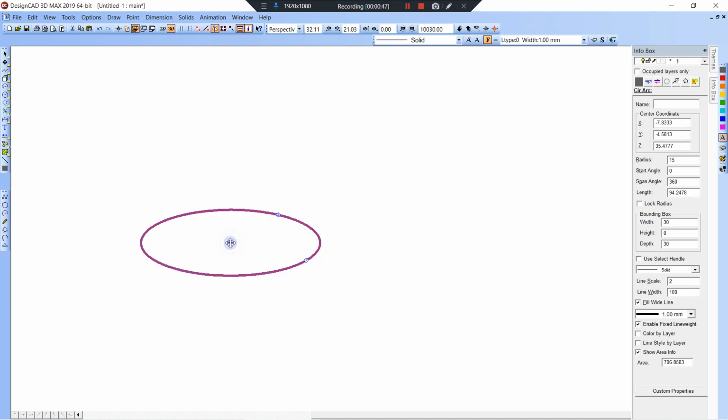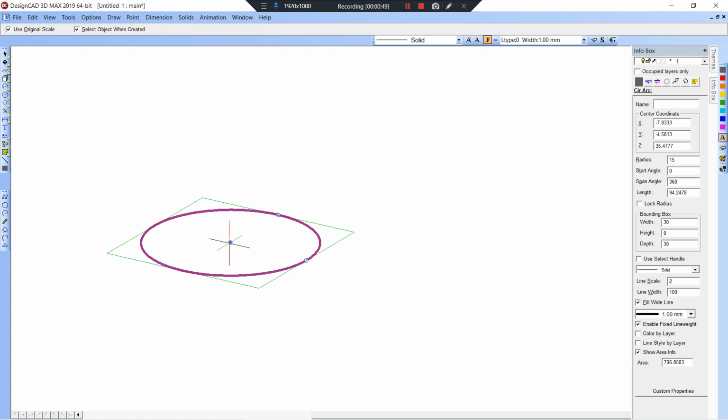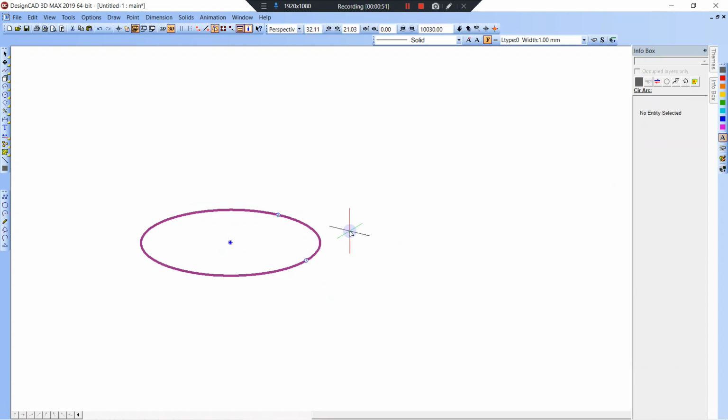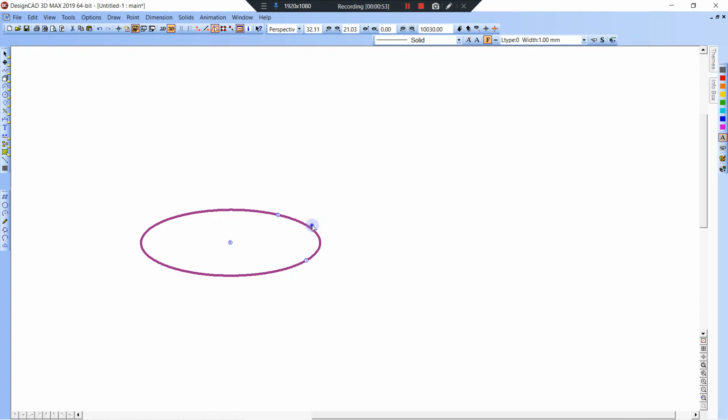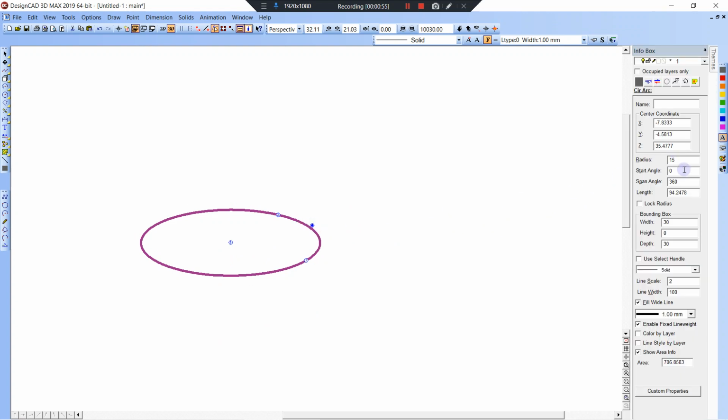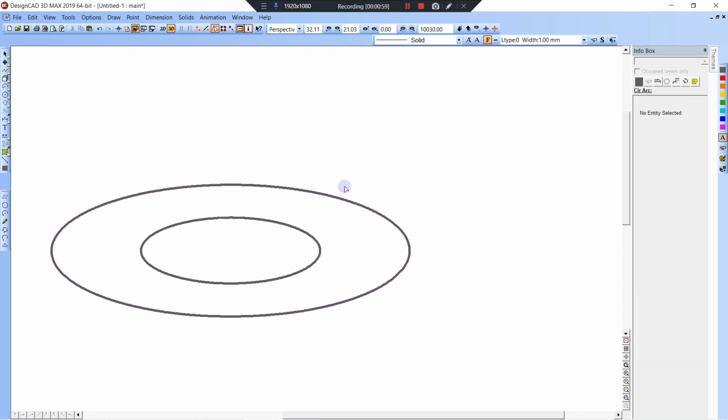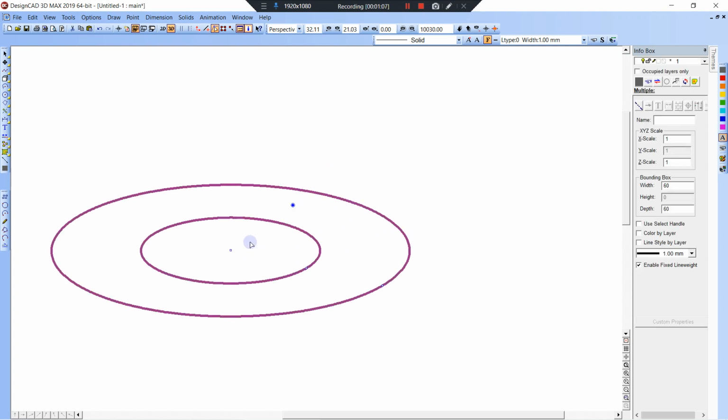And then I'm going to do a Control C, Control V, enter, and then Control I, and I'm going to do 30. So we have a 30-foot, 15-foot diameter inside radius, and about 15 feet in between there. That's kind of typical for a helix.